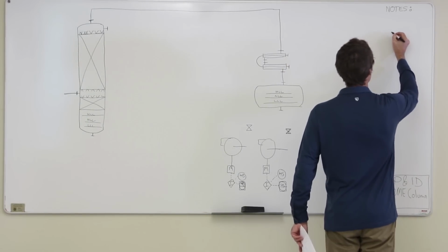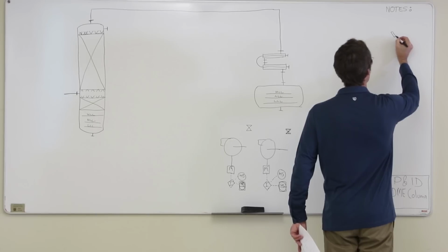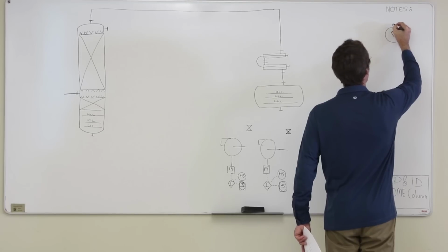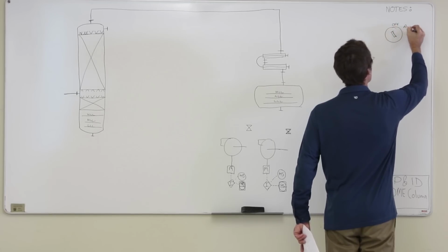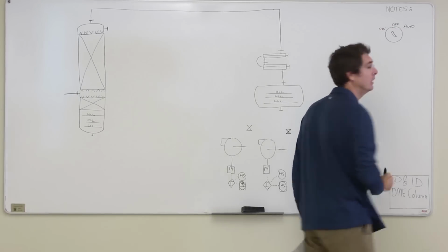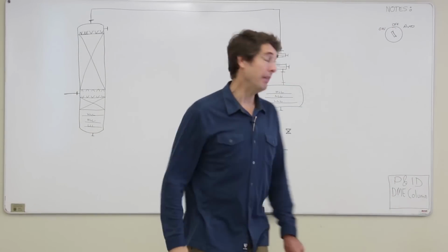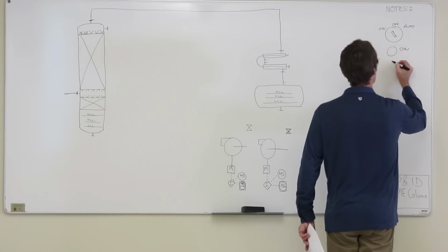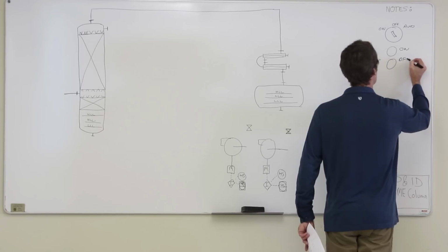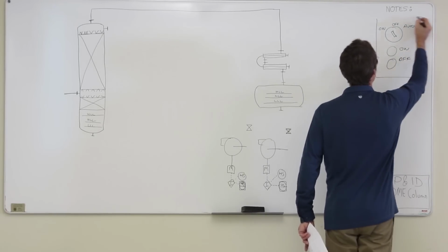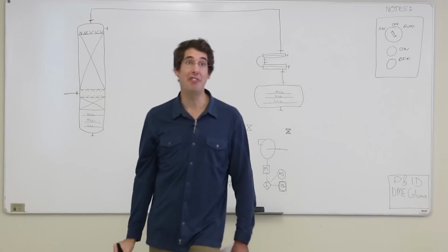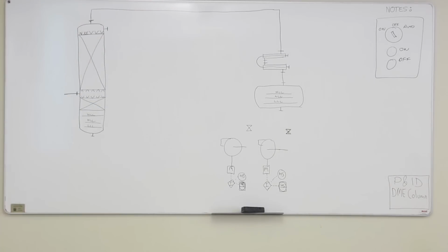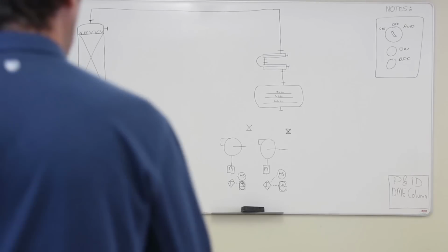A lot of them have basically a rotating lever like that, with an off position in the middle, an auto position, and an on. And on top of that you'll have a push button that's the on and a push button that's the off. So that's kind of a standard field-mounted control. It's shown like this, only the toggle for the auto on-off is missing.